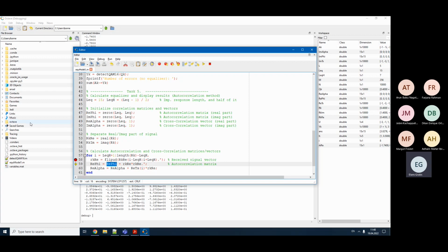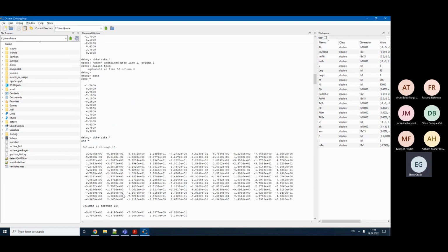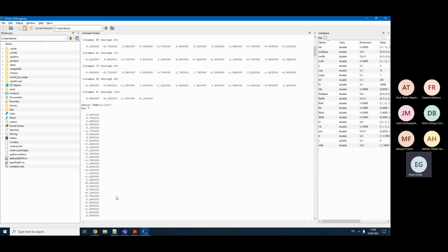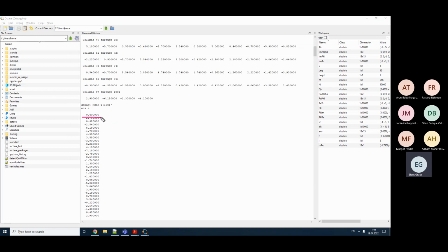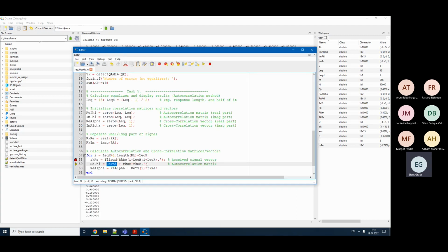So basically what is going to happen now is that at the next step we will take not really the first 15 symbols, but starting from the next, these 15 symbols, and recalculate the same autocorrelation matrix, add it on top, add it on top, add it on top, and go through all our data in this small sliding window, updating our autocorrelation matrix with each iteration. So that's how we calculate this total autocorrelation matrix.